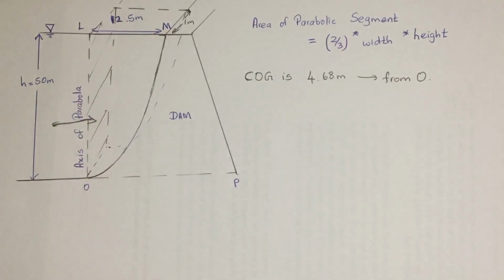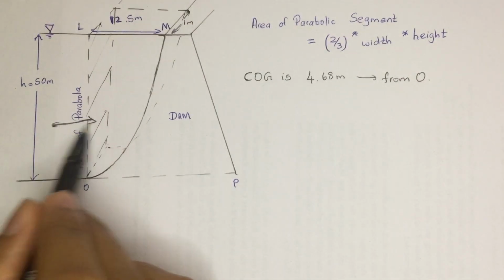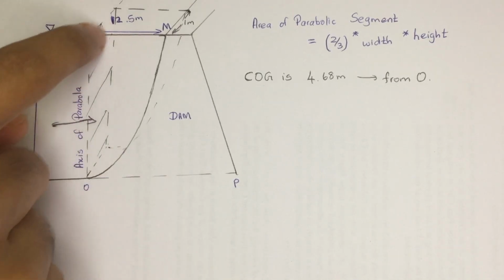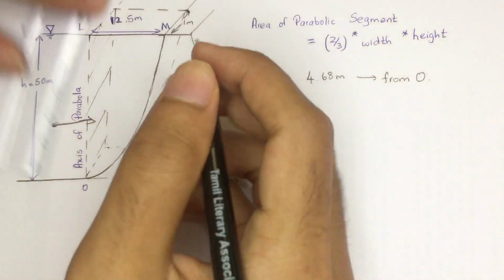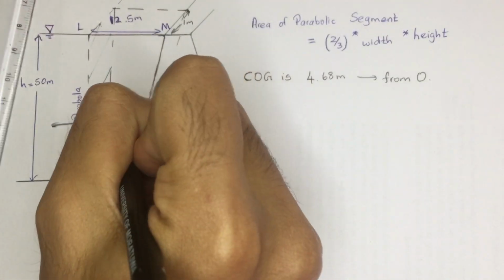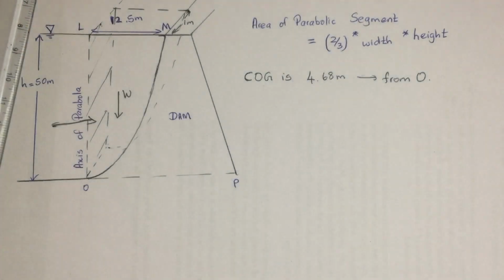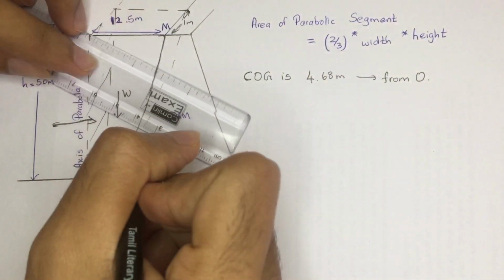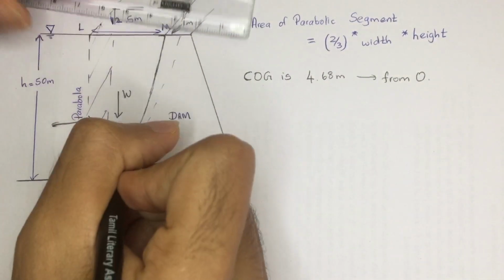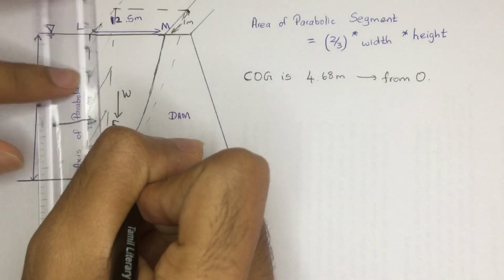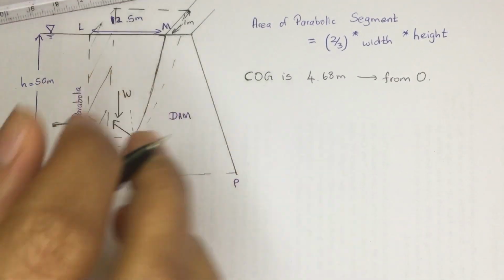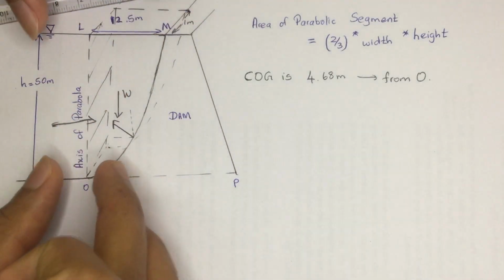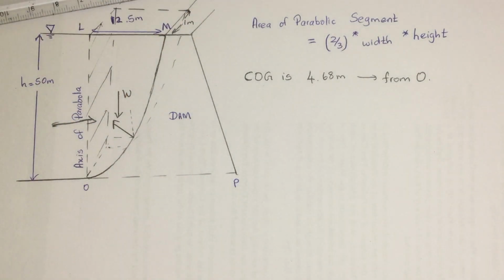When you consider this image, we knew that the force acting on this rectangular area is going to be horizontal, and the gravitational force is going to be in this direction, vertically downwards. The dam's force would be like this, which shows it also has a vertical component and a horizontal component to keep this water volume in equilibrium.